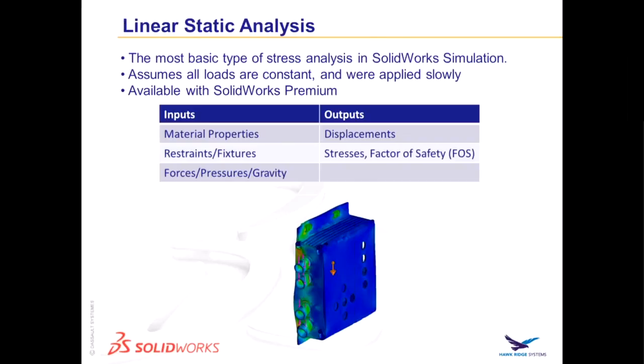So if you have any familiarity at all with simulation inside SOLIDWORKS, you may be familiar, for example, with something called SimExpress, which is inside every license of SOLIDWORKS. It allows you to do a basic stress analysis on a single part. Or you maybe are familiar with the slightly more comprehensive simulation inside SOLIDWORKS Premium, which again is a stress analysis, but it would allow you to do simulation on a full assembly with more types of loads and some more controls on the mesh and things like that.